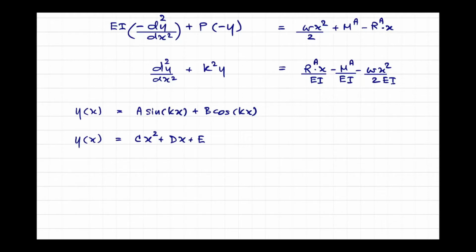So generally we use the accelerometers to pick up the dynamic information. Strain gauge can be used also. Displacement transducer is not good for the dynamic properties, but dynamic, you want to learn dynamic characteristic. Just that, you don't want to learn failure mode. You don't want to learn the ductility. Okay, so that will be the different kind of testing, and the purpose of the test is different.